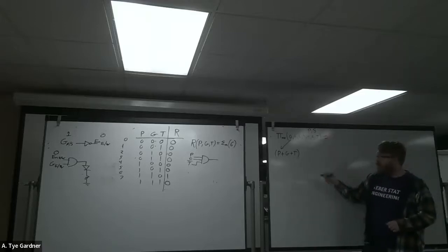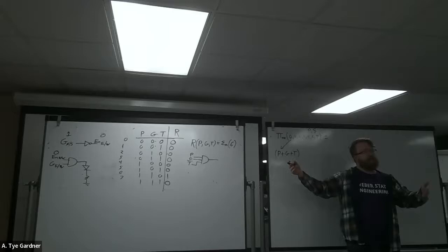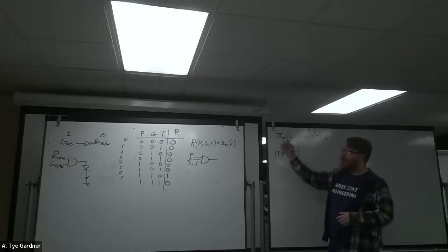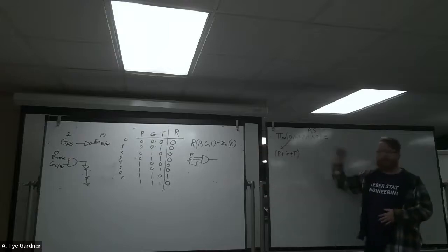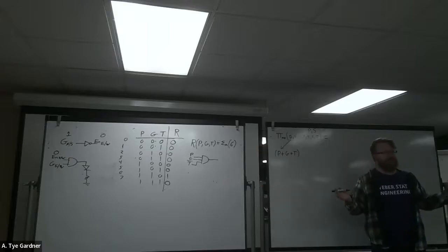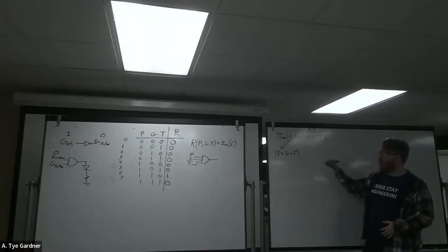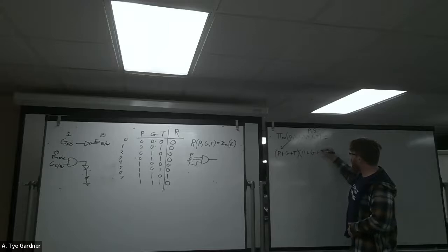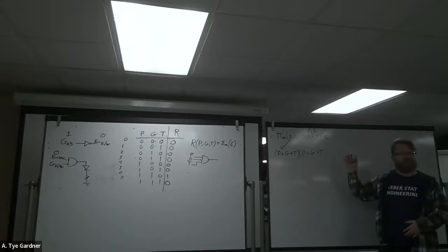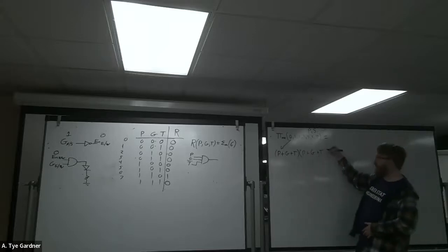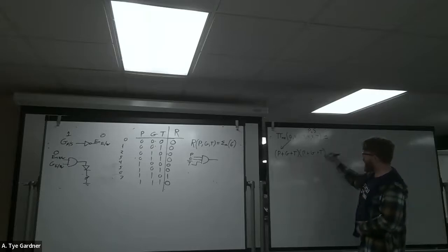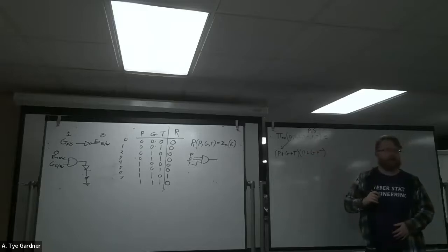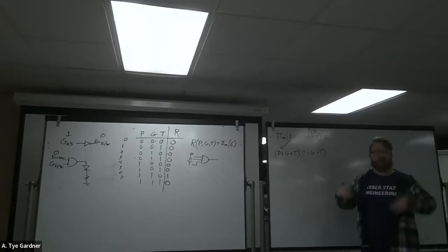And you're just flipping your gates. But the other thing is, where are the zeros, not the ones? Well, P, G, T are all 0. That means they don't get any not bars because they're zeros. Okay, it's just flipped. I flip the AND gates to OR gates, and then I start building it. And I need 7 of these product terms, right? Because there are, or sorry, sum terms, and they are multiplied together, product of sums. On the second row, there is a 1 on T for timer, which means it gets a bar. It's not T.